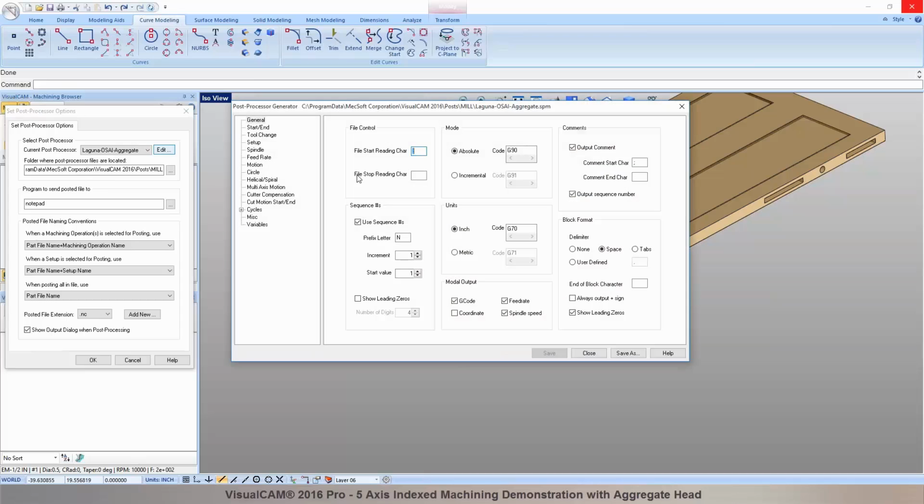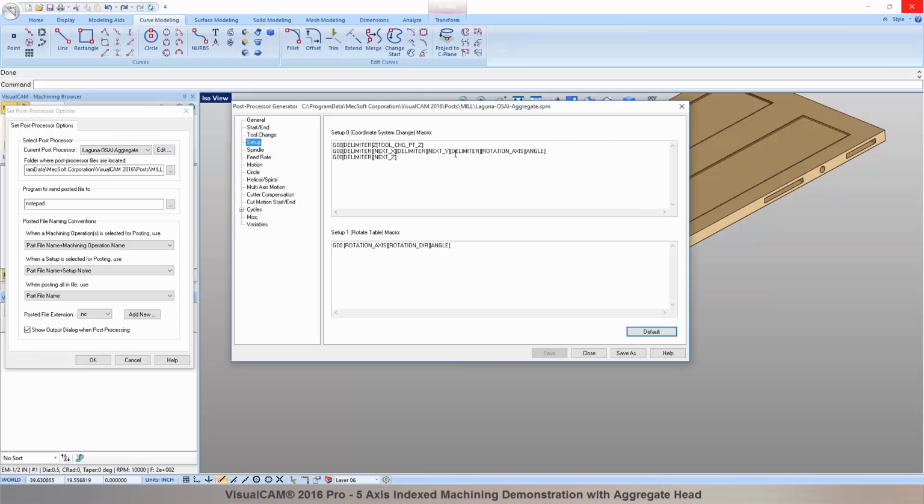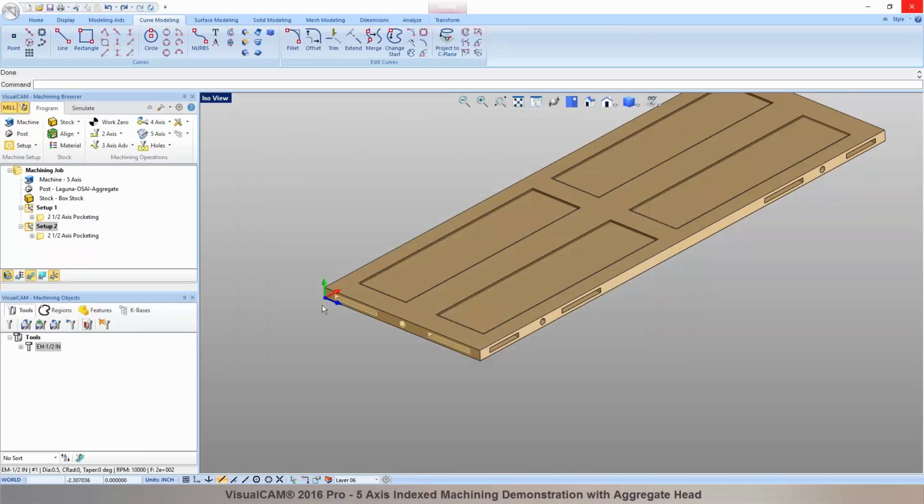We can go into the post processor. There's a setting. Gotcha. And then go over to the setup, and then we can exclude this C axis parameter from being output. I gotcha. Easy. Okay. Now all of your coordinates are still interpreted based off this origin right in here. So that's just the XYZ origin. Mm-hmm. So it's computing all your toolpath coordinates based off the origin that you define. So if you have the C rotate automatically, then you can basically post all the setups in one file.